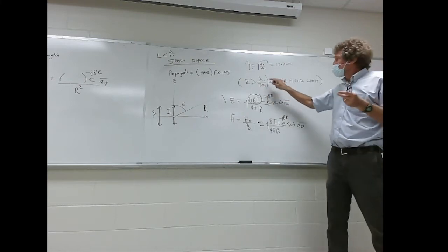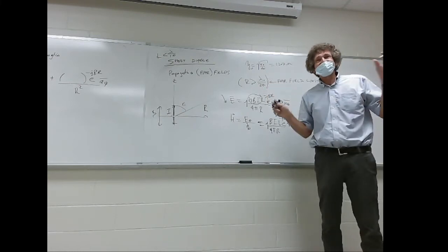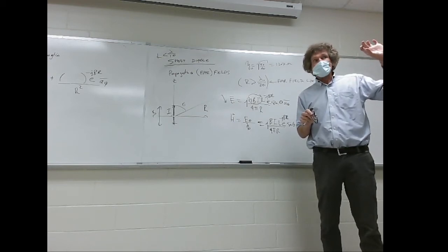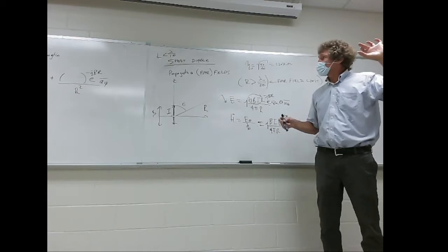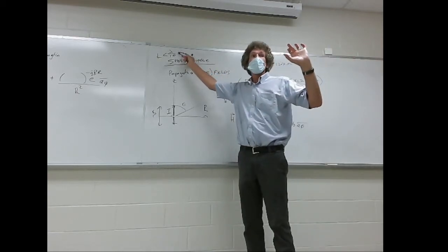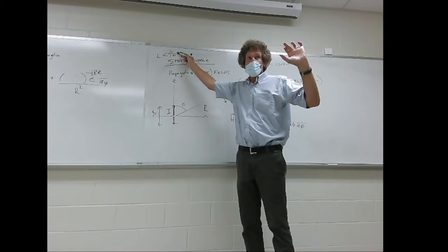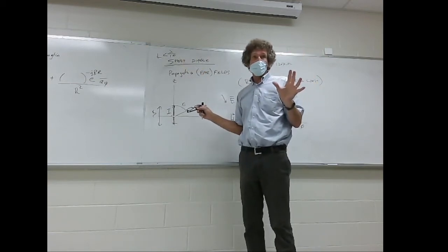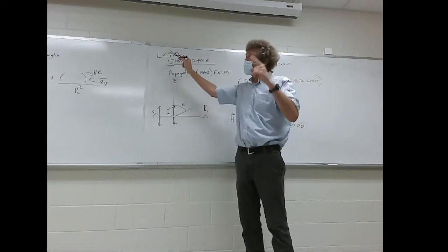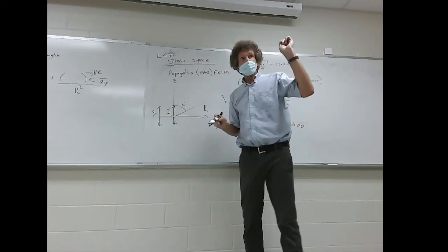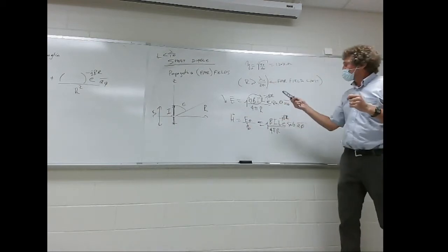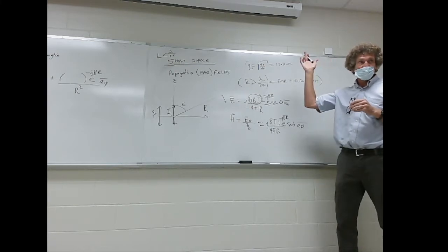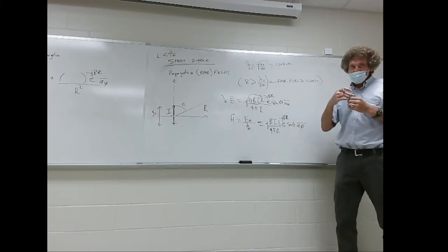Now you'll notice that this far field requirement has nothing to do with the length of the antenna. Please listen to me, right? What does have something to do with the length of the antenna is this assumption: the length has to be less than 1/10 of a wavelength. Got me on that? If it's not, then what we're doing here doesn't work. Then it's a longer dipole. But just appreciate, first, if your dipole meets this requirement, check the box. Then, to be in the far field, you have to be this far away. You with me? How many understand that? It's not hard, but you have to think about it.